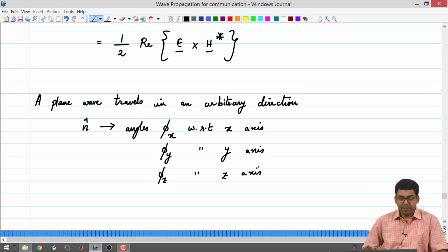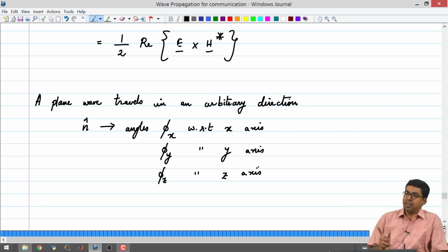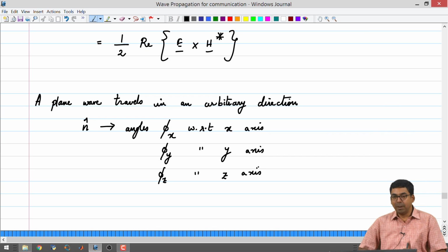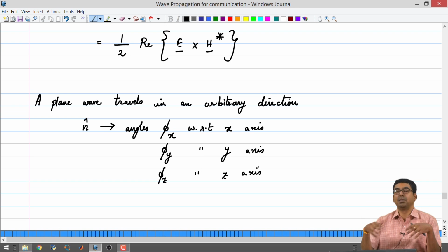please remember that previously when we were talking about plane wave, we made it very convenient in such a way that the direction of propagation was assumed to be z, you just assume the E field to be x oriented and magnetic field to be y oriented, alright. So, it was very easy, you had very few unit vectors in different directions to manipulate, but it is also possible that the coordinate axis is fixed, alright, and a plane wave is allowed to travel, you should be able to describe that also. In practice, it is a good approach to do either one, you can always orient your thumb to the direction of the travel and say that is going to be my z axis. In that case, you are defining a coordinate axis for the problem.